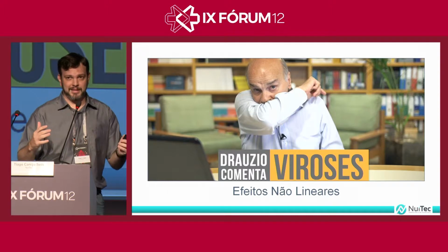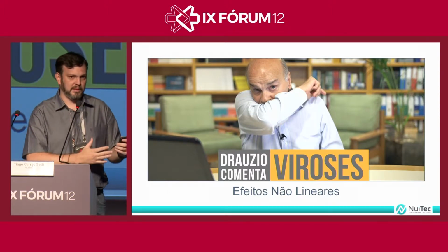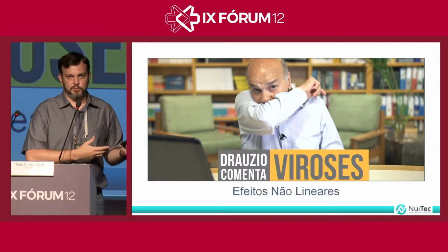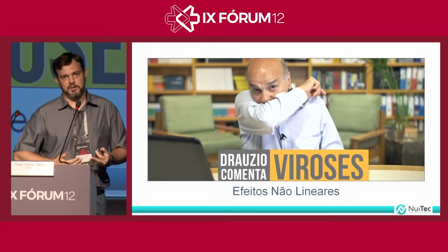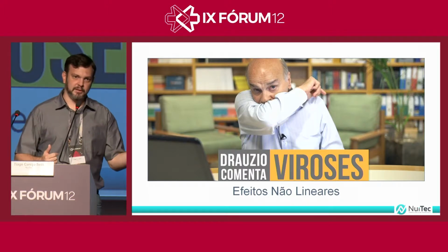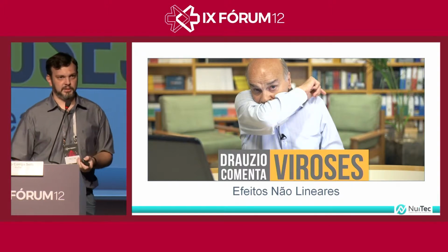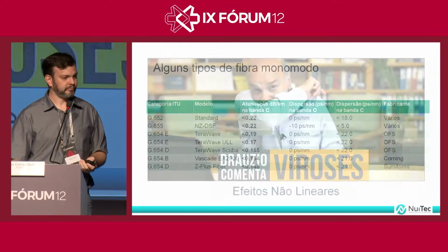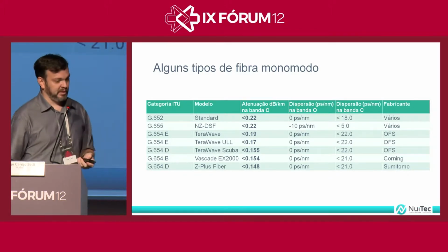And basically, if you try to summarize the nonlinear effects, they're connected to power in many channels. When you have many channels in one fiber and you have an effect, to diminish the nonlinear effects is to diminish the amount of channels, powers, and then you lose distance. And this becomes a challenge because here you will have to do the engineering of a link of a WDM.